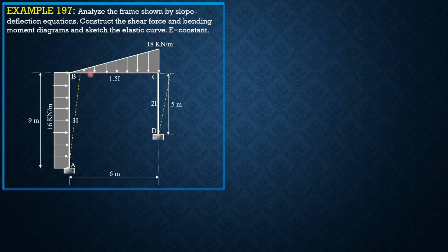We will denote this side sway deflection as delta. So this is also delta by compatibility equation. They have the same side sway. So we will express the slope deflection equation in terms of delta. That is, for both ends with moments, the moment is 2EI over L, quantity 2 theta near plus theta far, minus 3 times delta over L, then plus fixed moments.